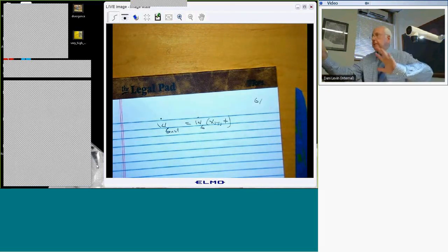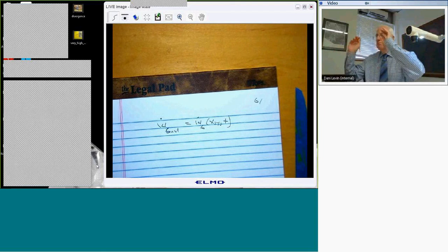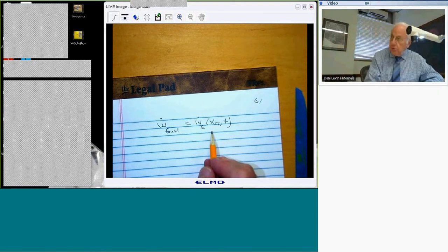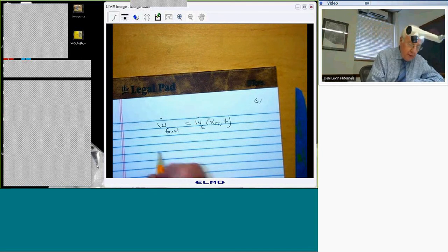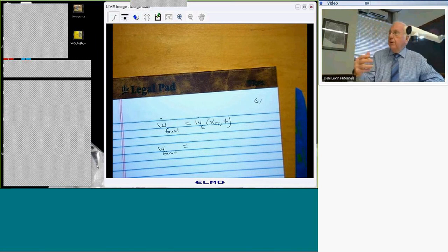Someone measured it. Someone who's an expert in meteorology told me what it was. But I could choose, if I wanted to, to represent the gust velocity in terms of a series of nice functions. And I might choose the eigen modes of the structure. Why? Because I am interested in how well the gust velocity distribution matches the eigen mode of the structure.